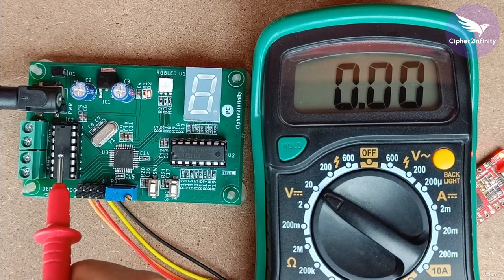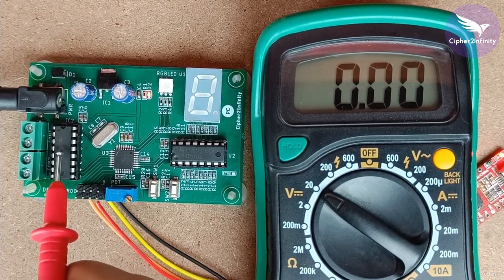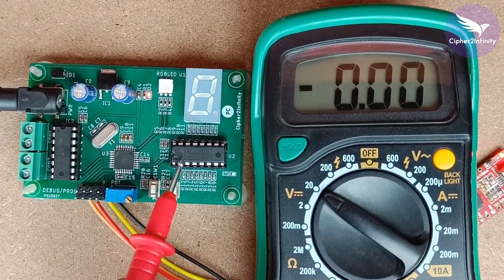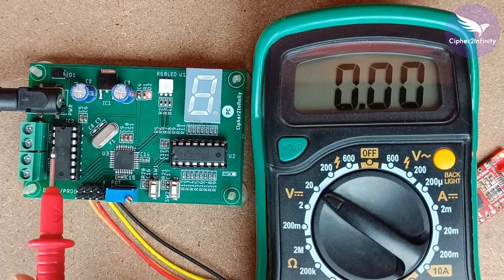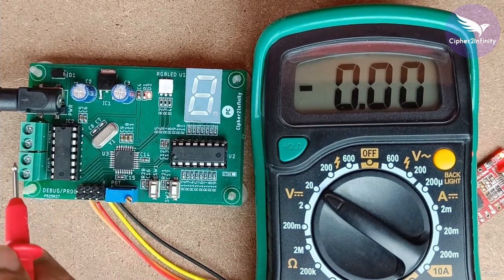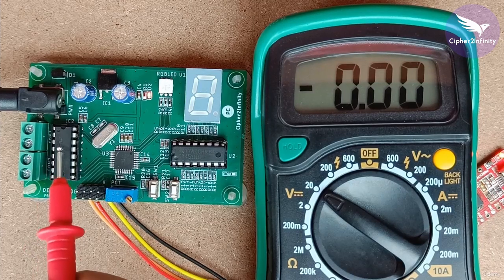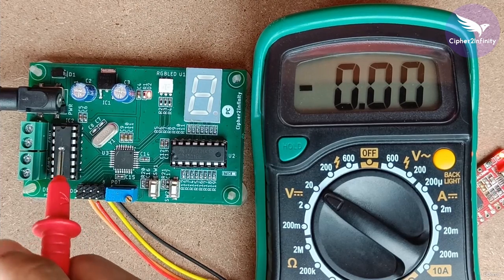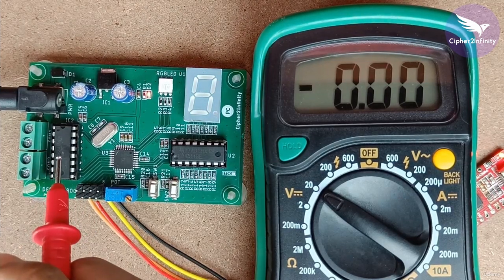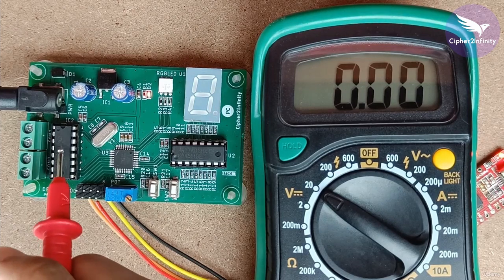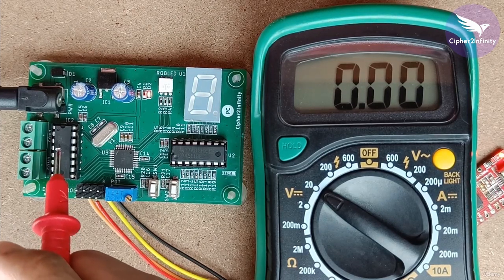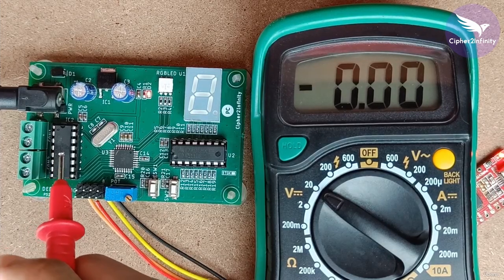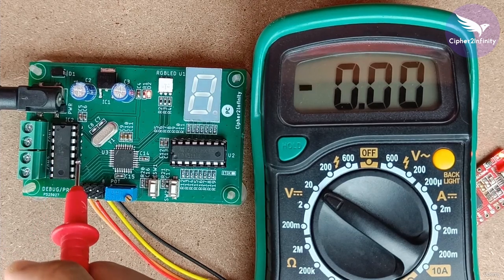After that, the third point is actually very important, and this mistake I didn't share with you when we discussed the 7-segment display section. This mistake is valid for this section and also for that section. Whenever you use a through-hole IC, always use an IC base for that particular IC. For example, if there is a problem with the IC, and you have soldered this IC directly on the PCB, you are going to face a lot of problems. You are going to face a lot of pain. So in order to avoid that kind of situation, you can always use an IC base.